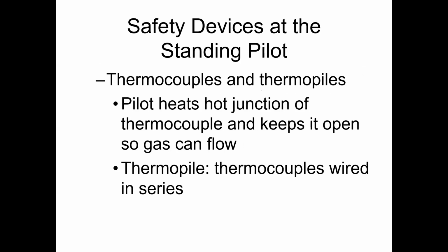So, safety devices at the standing pilot. Again, talking about standing pilots still. These are safety devices you're going to see in other styles of gas furnaces as well. I've seen thermocouples in direct spark ignition systems. I've seen liquid-filled bulbs in hot surface ignition systems. It just depends. For the standing pilot, this is where we're first starting to look and learn about thermocouples and thermopiles.